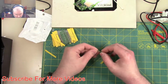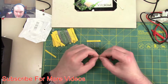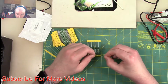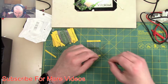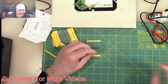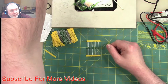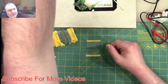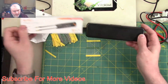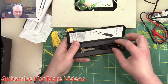Now, if you want to measure an inductor to see what its inductance is, you need a meter to do that. My desktop meters, believe it or not, being single-function test gear, and I'll show you my test gear right there, do not measure inductors. So you actually need an LCR meter to measure an inductor, and I happen to have a pair of Elite One, made in Canada, LCR tweezers here, so I'm going to use these.